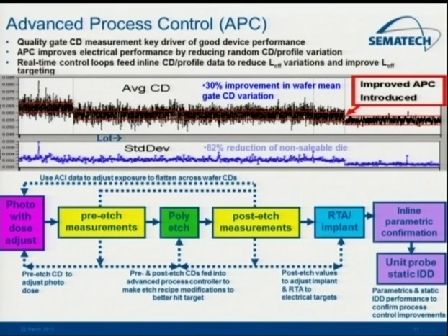For example, if you have a lithography step that you print the small features with your lithography tool, do a measurement before you etch it, do an etch step, do a measurement afterwards, continue on with regards to completing the device, you can actually take those measurements, and if this is too big or too small, you can feed that backward to make adjustments for the next lot. That's kind of a feedback loop.